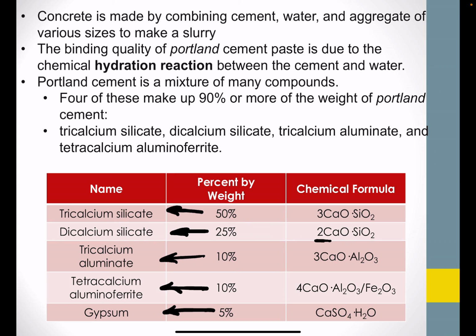And in the last, in the aluminate, we've got a 3-to-1 ratio there of that calcium oxide to that alumina. And in the final aluminoferrite, we have a balance between alumina and the Fe2O3 against 4 units of the calcium oxide. And again, the formula of gypsum is listed below. And again, there should be a 2 there. Apologies for the error there.